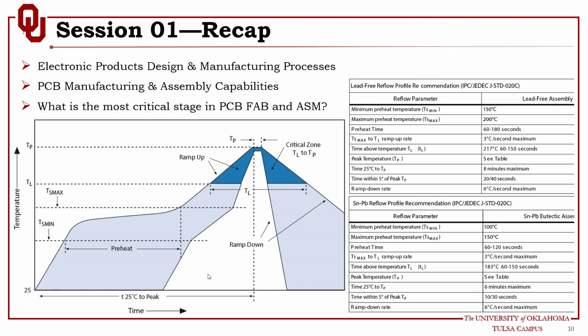The first stage is called preheat. Basically, in this stage, the flux solvents are evaporated, and your board is quickly brought to a little bit more than half the reflow temperature.